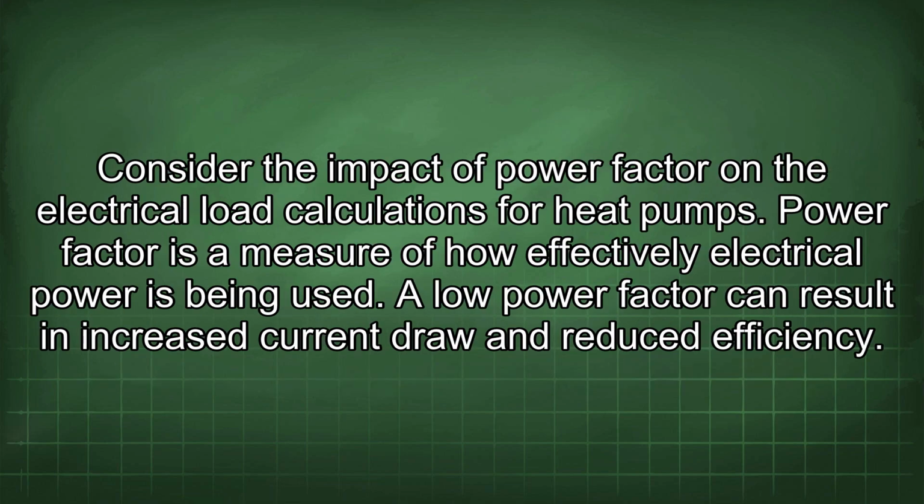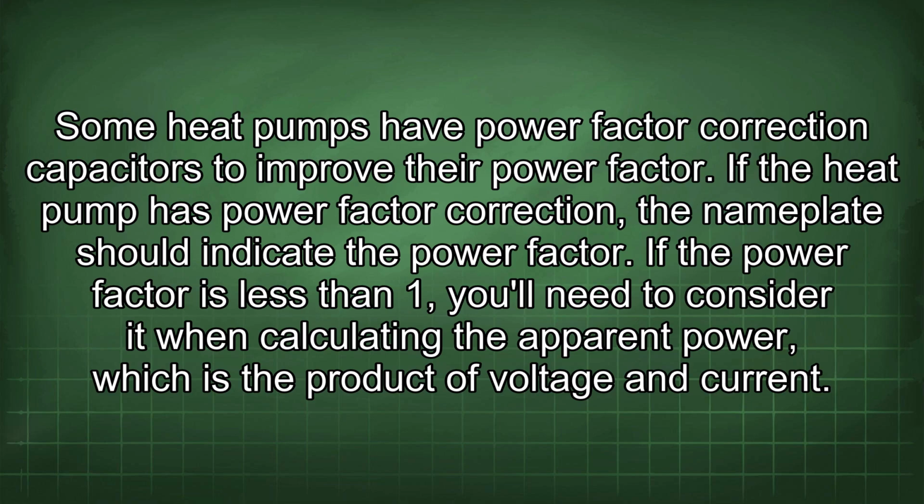Consider the impact of power factor on the electrical load calculations for heat pumps. Power factor is a measure of how effectively electrical power is being used. A low power factor can result in increased current draw or reduced efficiency. Some heat pumps have power factor correction capacitors to improve their power factor. If the heat pump has power factor correction, the nameplate should indicate the power factor.